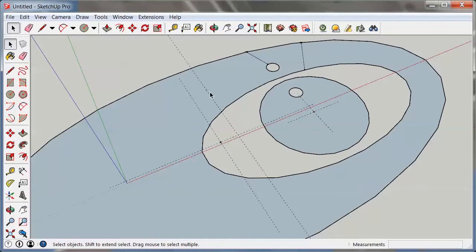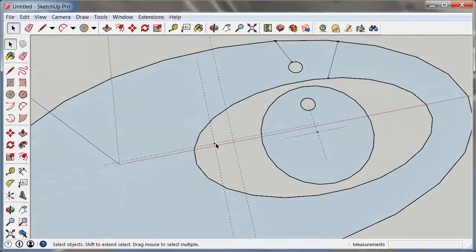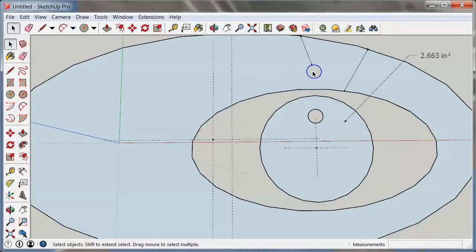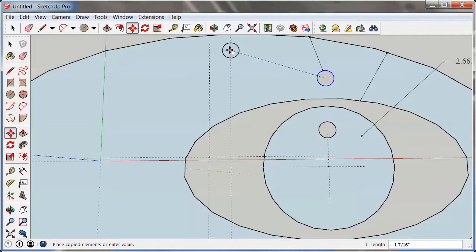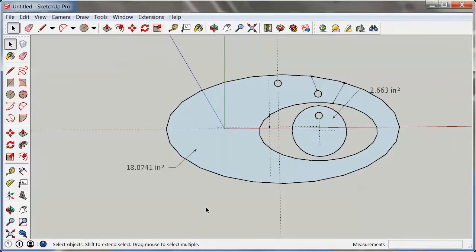Okay, so the location is right here as a temporary line. I got my two centroids, one here, one there, and there's that. And then all I need to do is copy my hole right onto that line, again a little further up so that everything hangs nicely. And I'm going to hover over the side of the circle so that I can actually get its center. And again, you don't want to move this thing, but hit Control so that I copy, and then all I need to do is go onto this line, a little up, maybe right there, and I got my suspension point.